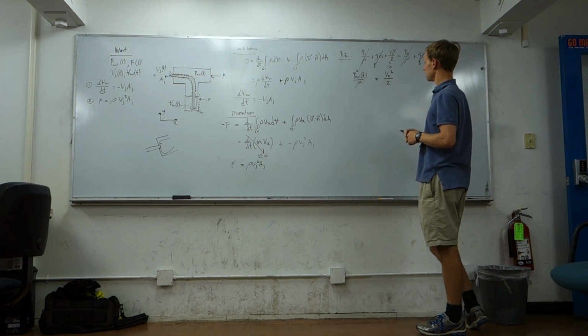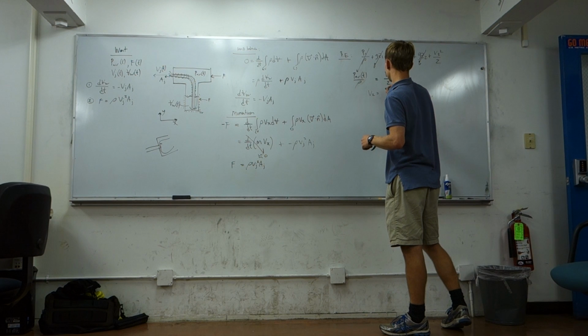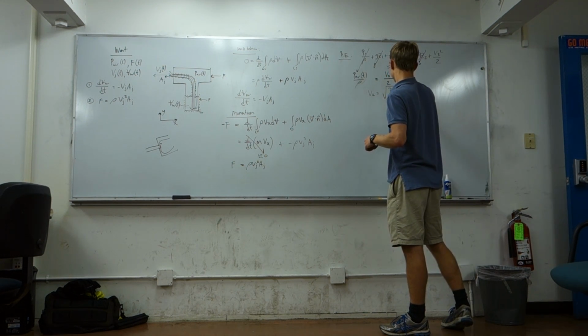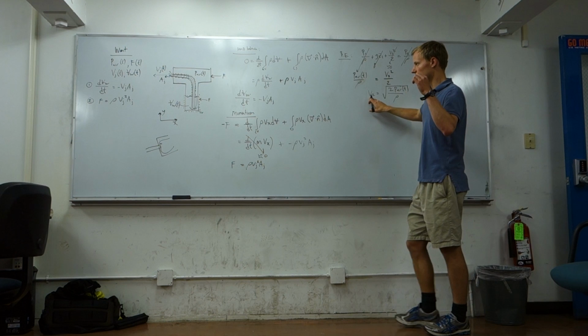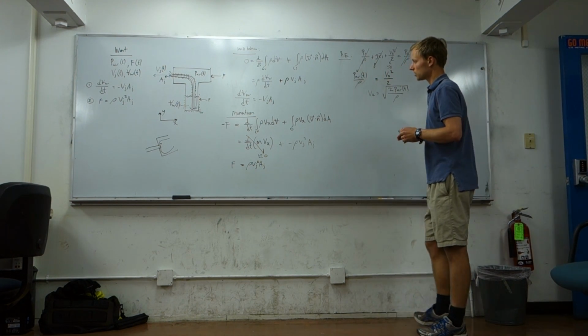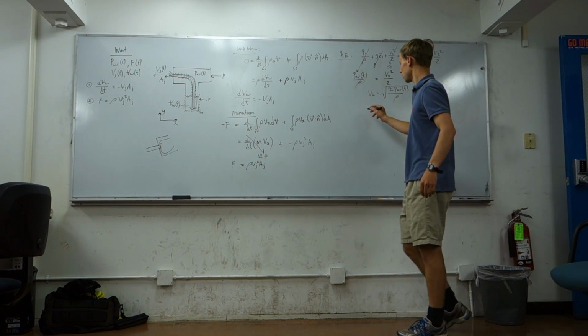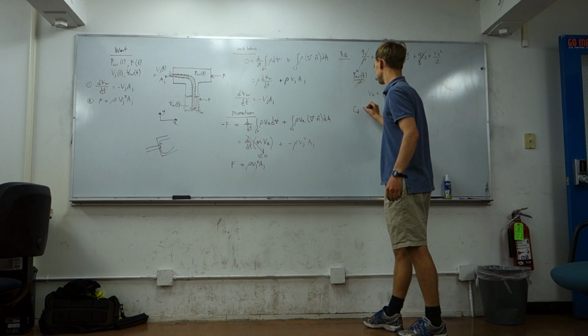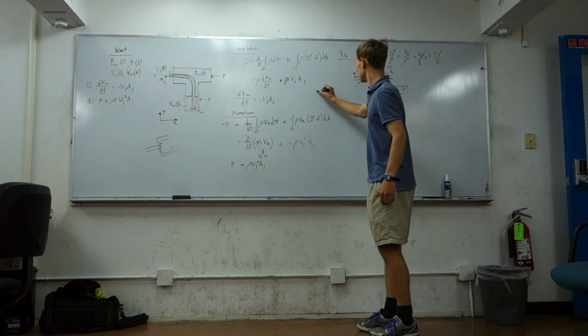Now here's where we need to, well, not quite yet. So we'll solve for V2 really fast. V2 is just the square root of 2 P-air over rho. But this velocity here assumes inviscid flow, no losses in our nozzle. Turns out this nozzle business is not negligible. We need to account for it. So we'll use what's called the discharge coefficient, C sub D, which is defined for, start over here again better.